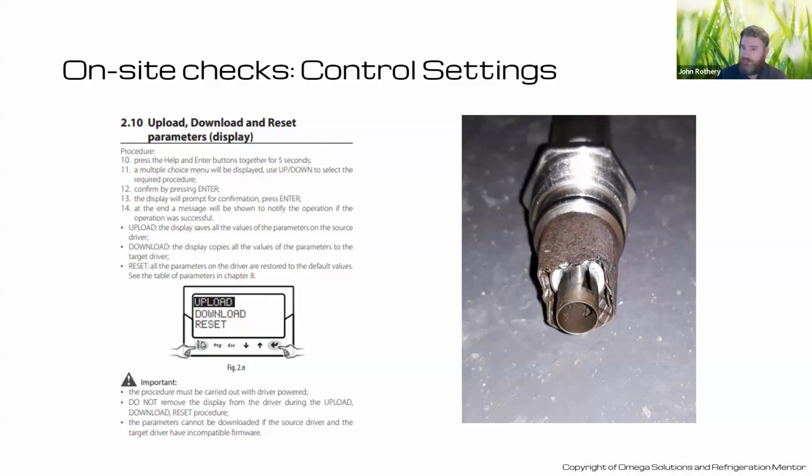Yeah. And that text to the side of that shows the ability you've got with, I think it's the Carel EVD Evo, where you have an interchangeable display. You can actually upload the settings to the display and have that as a backup. So if that valve driver ever fails, you can take the display off, put it back on, download the settings, so it saves you a lot of time. Equally, if you've got another pack on site with a second display, you can upload it and transfer it across. As long as it's the same system and it's commissioned the same, it can save you a lot of time and headache. So, love that.